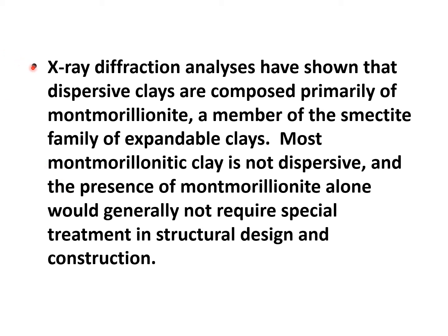X-ray diffraction analyses have shown that dispersive clays are composed primarily of montmorillonite, a member of the smectite family of expandable clays. Most montmorillonitic clay is not dispersive, and the presence of montmorillonite alone would generally not require special treatment in structural design and construction.